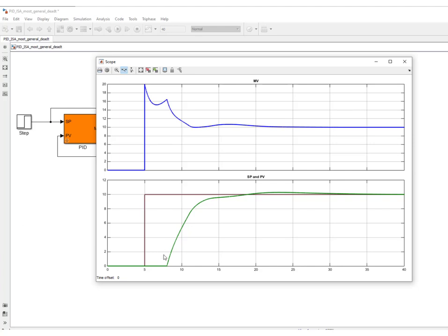C is equal to 1. And then when the system reacts, well, you have the D kick on the other side. So here you have proportional, derivative, and then integral part that kicks in, and then the process reacts, and you have here the D kick on the other side. This is coming from the change of PV.